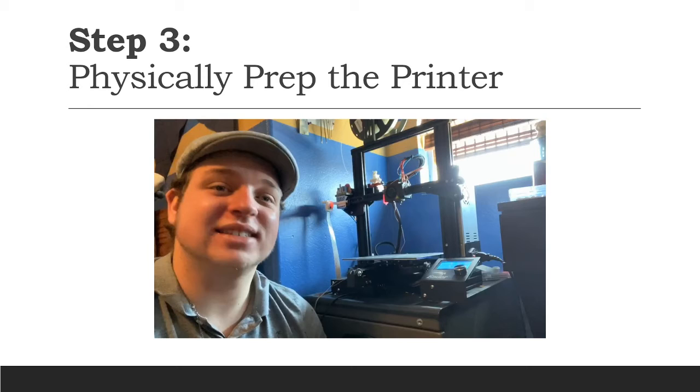Last thing you're going to want to do is to make sure you have the right nozzle. As I emphasized before, in Cura settings, we said that we had a 0.4 millimeter nozzle that we were going to use. Right now, I have a 1 millimeter nozzle that I am using. So we're going to really want to make sure we change that. I have a little box of nozzles here that we're going to use to make the change real quick. Once you have that completely on, you should be good. You might want to feed in your filament a little bit, but that doesn't really matter because of the extra layers it puts through, so you should be good there. So now, give it one little extra tug on there, and your printer is completely prepped.